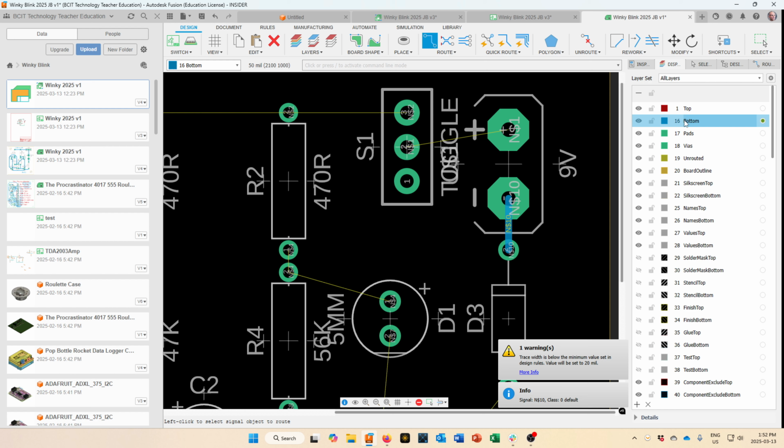The computer kind of gives us an X-ray vision that lets us look through all of the layers at the same time. And we're putting all of our copper on the back because our components are going to go on the top. So we'll look at this from the top. Later on, we'll get into using two-sided boards and we will put things on the top layer and we will have vias that go through the board to connect them.